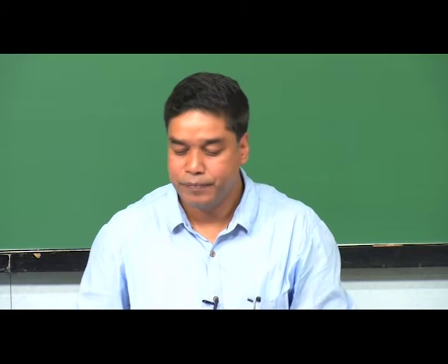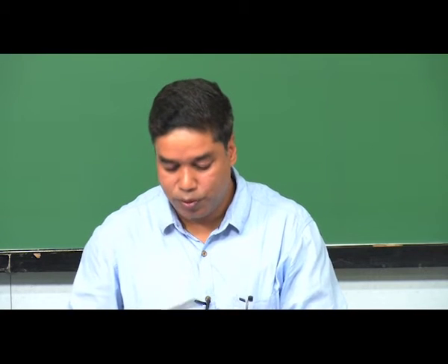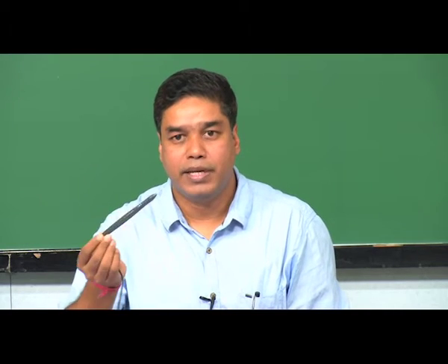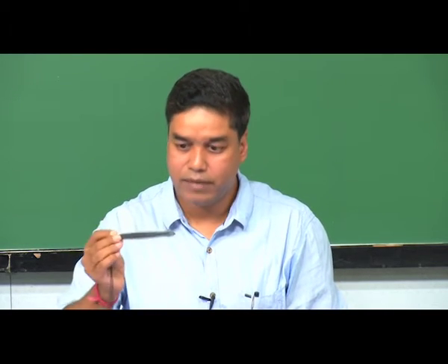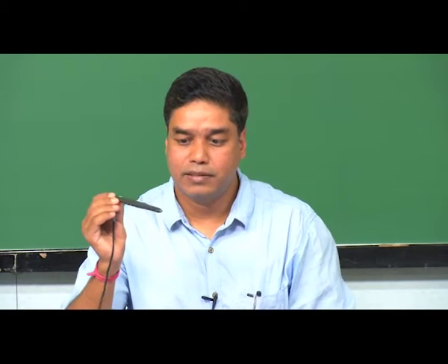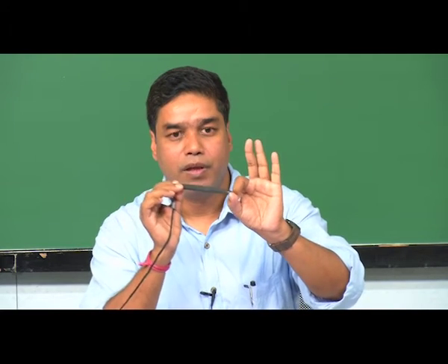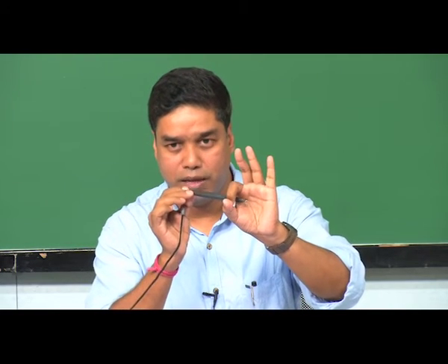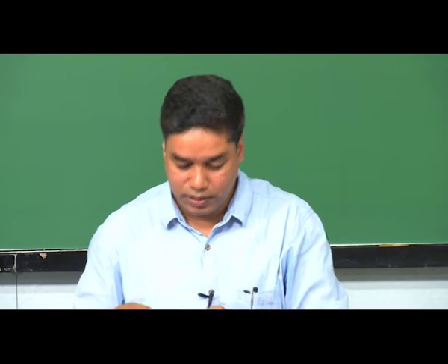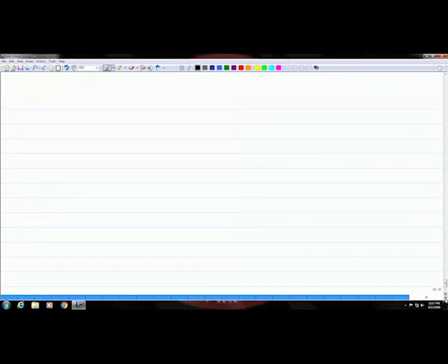of the part. Okay. So, the probe might just look like this pen. If you have a look at this pen, many times eddy current probes have this kind of geometry and this kind of appearance. So, you can take this, and if you have a hole like this, you can put it inside the hole diameter, the inner diameter, and you can inspect the circumference. So, these are the bolt hole type probes.